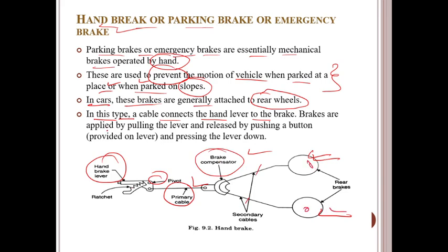So brakes are applied by pulling the lever. We just move this lever, and release by pushing a button provided on the lever and pressing the lever down. By the motion of pressing, we just move the lever up or down.